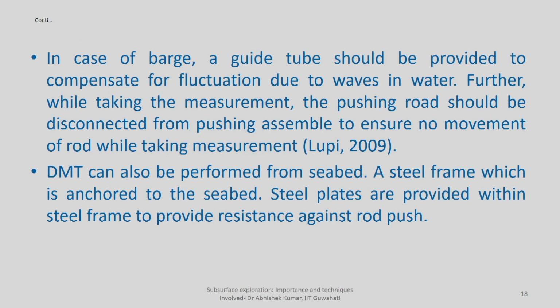In the second case, if you are doing the DMT test by means of a barge, you have to provide a kind of guide tube that will minimize any possible fluctuation in the wave heights on the reaction provided to your testing. Further, while taking the measurements, every time you make a measurement, like applying pressure for 1.1 mm disturbance or pushing into the soil, every time you are taking a measurement, you connect your push rod with your pushing assembly. That will ensure your field measurements are minimally affected by fluctuation in water height.